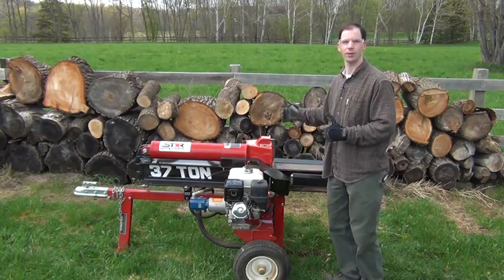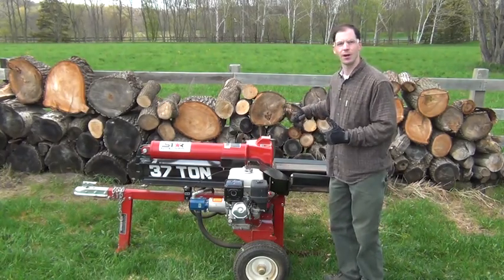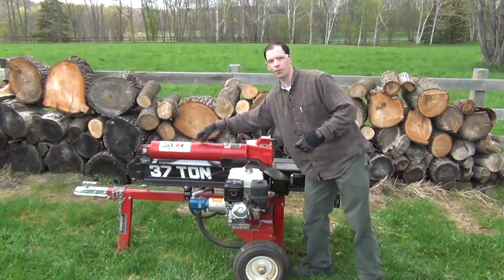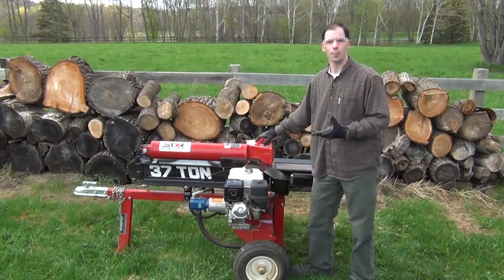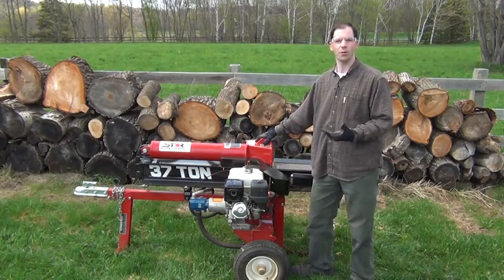And you'll see the difference in the cylinder velocity due to the difference in the cap side versus the rod side area of this hydraulic cylinder. Next, to start really exploring what the pump's doing, I'm going to change the engine speed as we're moving.